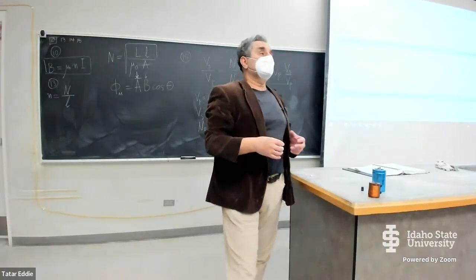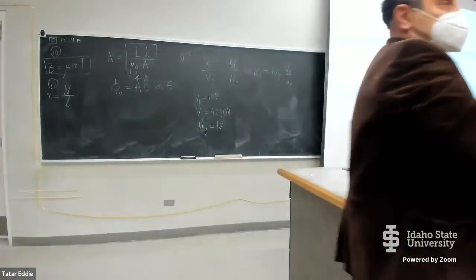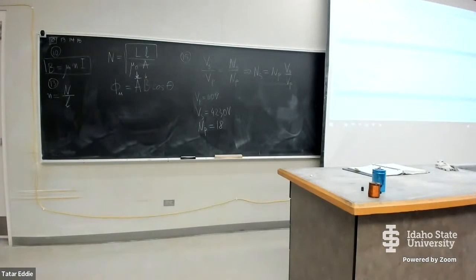So when the secondary coil has a larger number of turns, you have higher voltage in the secondary circuit, and you have a step up. So if we had started with 110 and then the secondary was like 11, that would be a step down transformer. Yes, that would be a step down transformer, but it's not going to work.